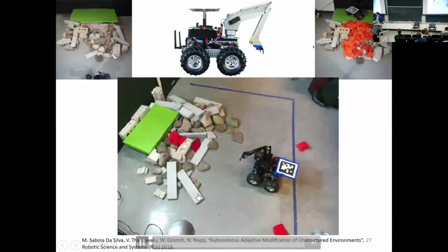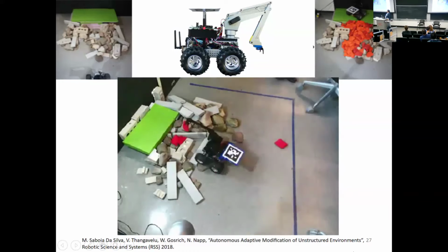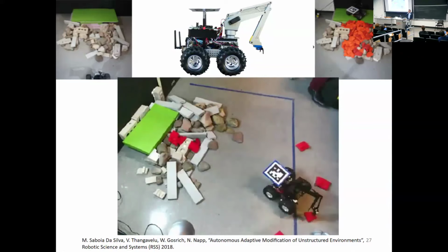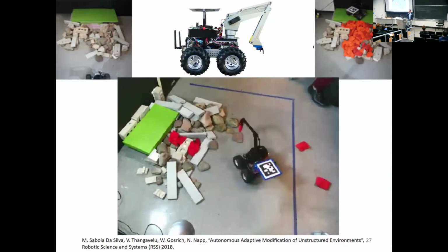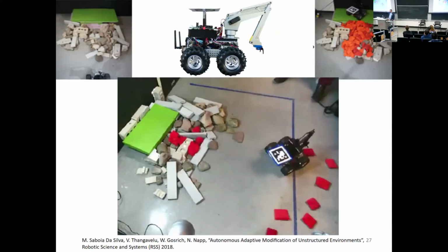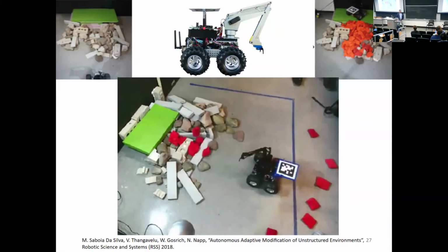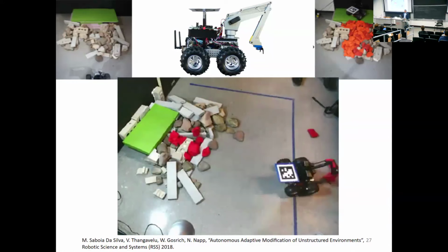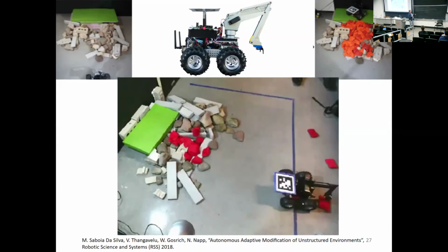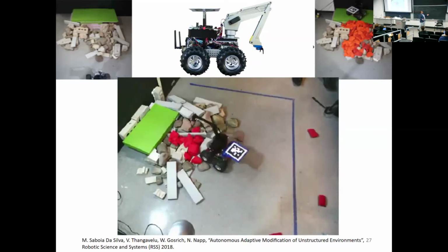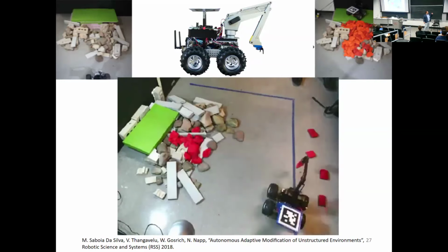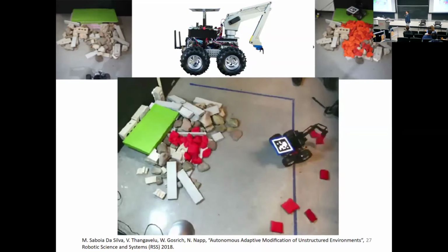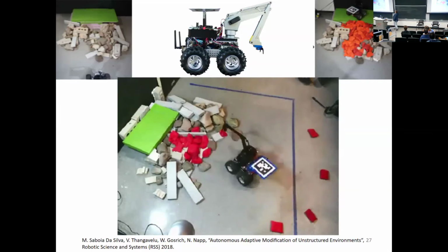which I'll start automatically. So this is a sped up experiment of a robot grabbing bags. And the robot just follows the same rule, right? It grabs a bag. The bags are smaller than the epsilon deposition that we computed for the navigability of that particular platform. And the robot just keeps doing that. And it's sort of reactive, in the sense that every time it rescans, it's a new scan of the environment, then it decides where the next deposition should be. It makes it, and then it just continuously tries to achieve navigability towards the goal.